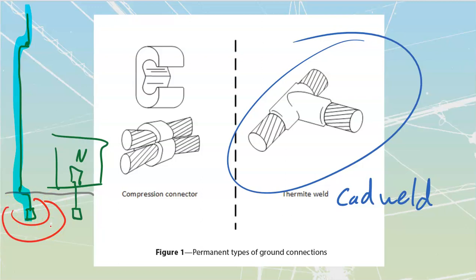Now, past about a meter and a bit, they don't really form anything that significant. However, if I would have kept these two tightly close together over there, what would happen inside of my building is that this lightning, instead of wanting to run all the way down this to where it's got this potential over here, some of it would divert into the building wiring system and run back down to that, because it sees that it's getting ultimately back to that same point, and that same point is going to be easily accessible by just breaching our insulation. Insulation for NMD is only 300 volts. So we want to keep these things far enough apart so that we don't get any cross breaching anytime that we get that carried down through.